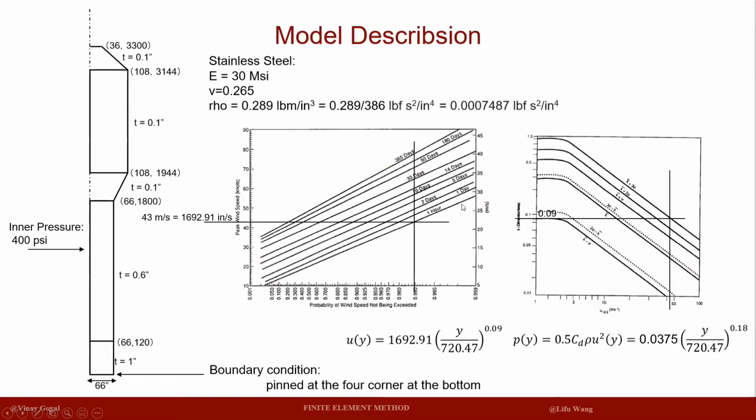exciting tutorial. Hello everyone, welcome to another finite element tutorial about modeling of a launch vehicle. And here's the problem statement. You already see it in your project Word file. So I've converted all the units into pounds, inches, and seconds, because some of the units are meters per second. And here's the result. So this is a model. This is the symmetric axis, and we are going to use 3D shell for modeling everything.